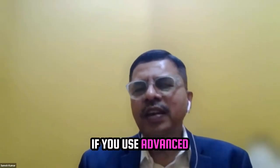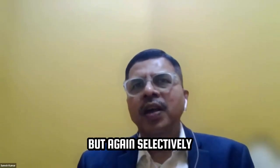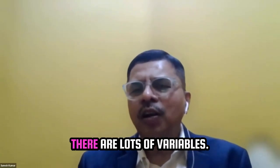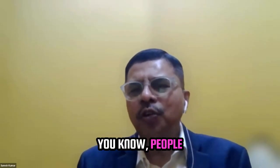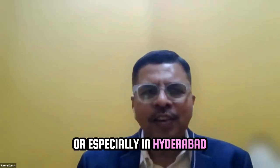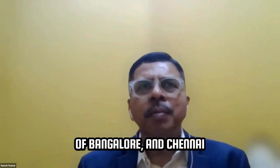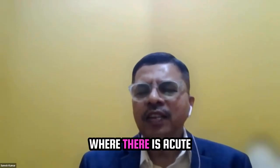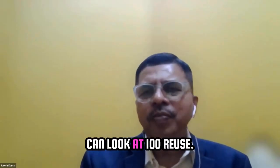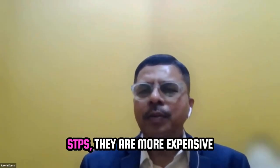Right? If you use advanced processes, you can reuse 100% of the water, but again, selectively. There are lots of variables, people should be ready. Not many of us are. We don't have that kind of water shortage in India, or especially in Hyderabad or places like Kerala. It is there in some pockets of Bangalore and Chennai, where there is acute water shortage. Then they can look at 100% reuse. Otherwise, I don't recommend 100% reuse STPs.